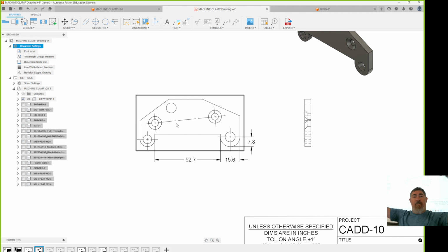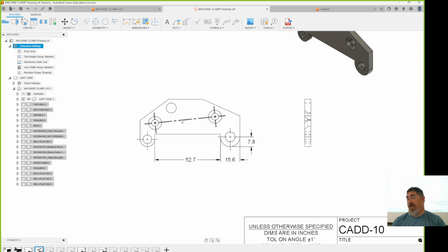They rely on each other. If this spacing on one part is different than the spacing on a different part, they're not gonna work, right? So you could do that center line like that, just to show that, hey, these two things are connected. You have to? No. But you could do it just to provide that relationship. So that's part of what we use center marks and center lines for, is establishing relationships between features. Okay. That make sense? Yep.